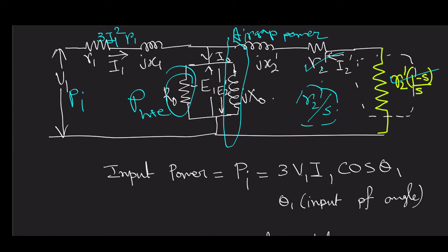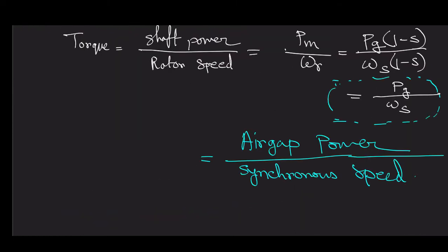I will try to highlight the fact that even in the worst condition, the flux is 92% of its no load flux or unaffected flux. So this branch can be taken here. So I would like to go for an approximate equivalent circuit like this.